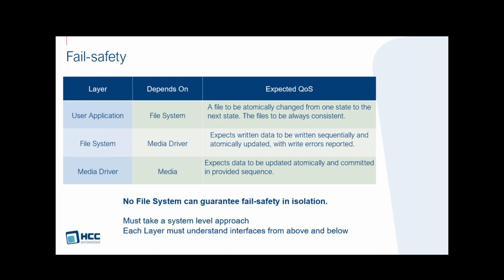If you look at how a standard SD card works with multiple dies and data being written in parallel, you cannot guarantee the sequence in which sectors are written to the media. And so if they get switched off unexpectedly, you could get a jumbled sequence. You might have two sectors not written, the next two sectors written, the next two sectors not written. There's no file system logic that will ever save you from this problem, unless you have some kind of RAID array that's separately looking after this. There's no way that you can produce logic that can deal with a random series of written and non-written sectors.